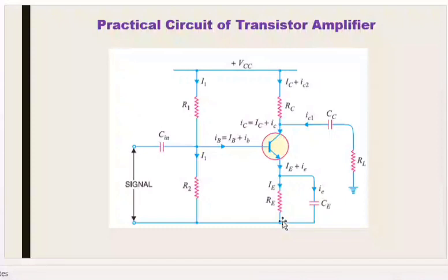After the drop, you will not get the maximum output. That's why we have connected this emitter bypass capacitor. Okay, sir, is it clear?